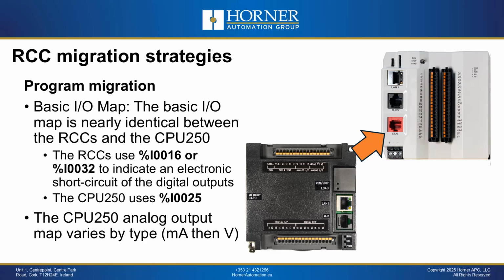And then another case where remapping may be required is in the case of analog outputs. If you are using voltage analog outputs, you may have to do a remap of your AQ registers as well, because of the way that works with CPU250.